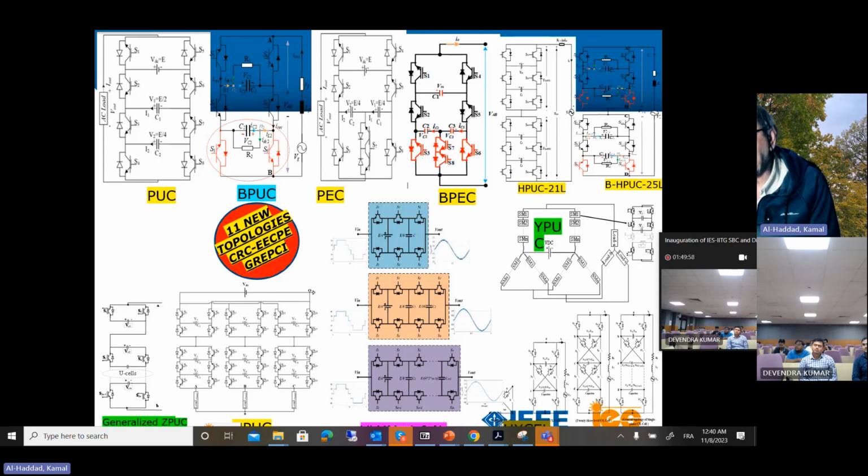Also, with the new wide band gap technology, with fast switching and high performance, we are hoping to greatly reduce the switching losses and the conduction losses. With these topologies, we're not switching at high frequency, we are switching at very low frequency. We don't worry very much about frequency-related losses, though for these topologies the first 2 switches operate at the fundamental frequency, but the last switches, which have the least voltage, operate at higher frequency. So we end up using a low-voltage, high-frequency device, but still not operating at 100 or 200 kilohertz. We're operating at about 10 kilohertz and less, and we have a beautiful, well-controlled sine wave output voltage.